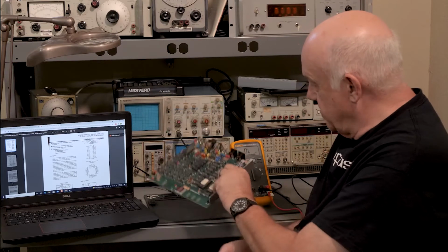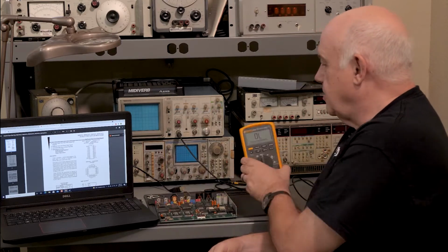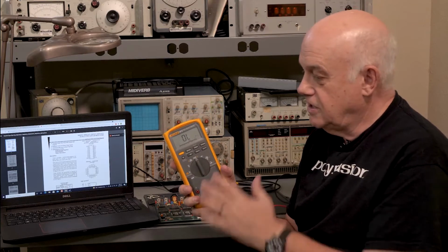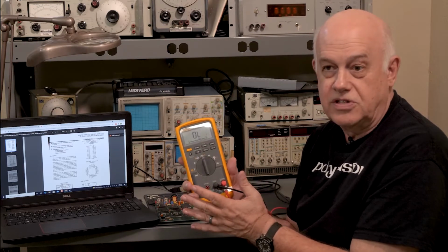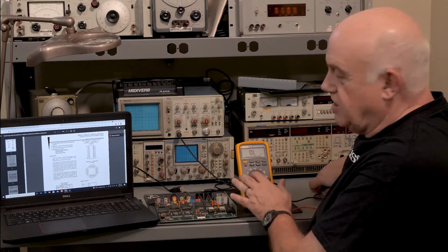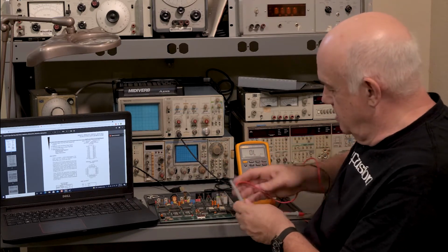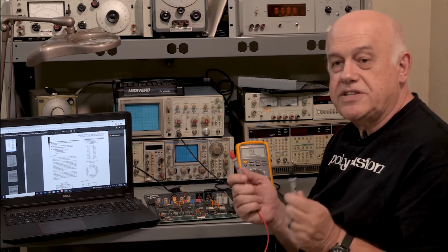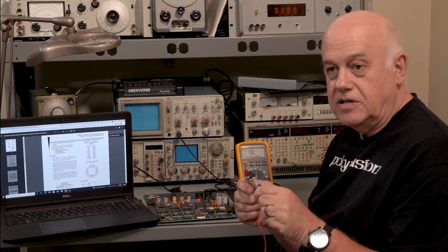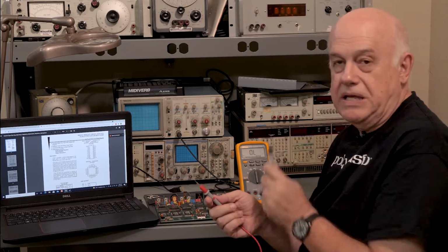So how do you even begin reverse engineering something like this? Well, it turns out that all you really need is a little voltmeter. And you're not going to use it to measure volts or resistance per se. We're going to put it in what's called beeping continuity mode. So what this means, if you just take the leads and you touch them together, you get a beep.